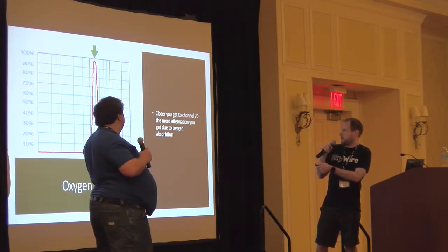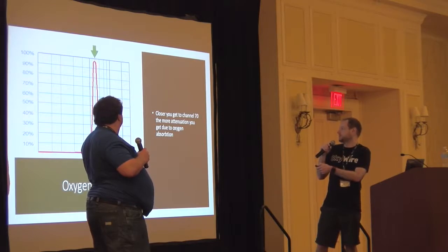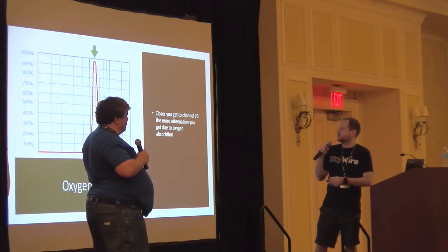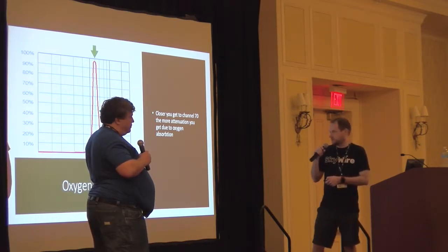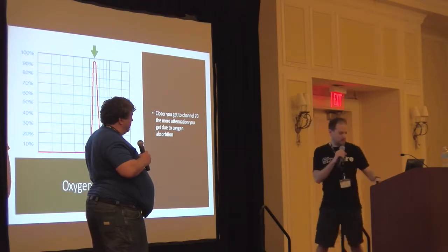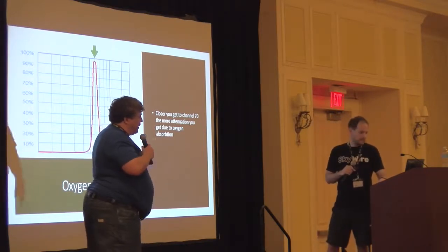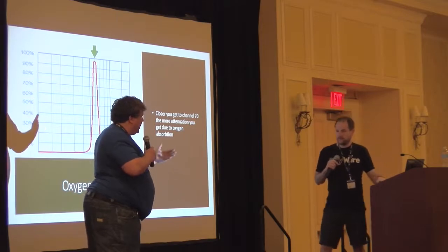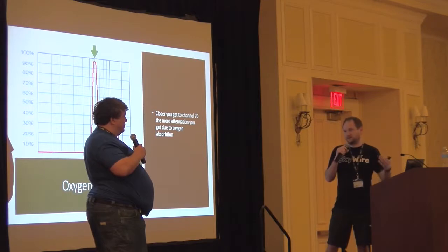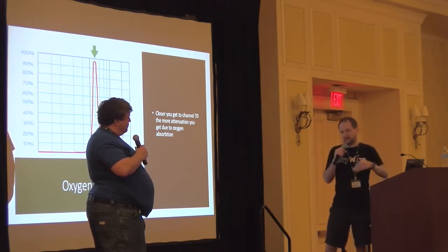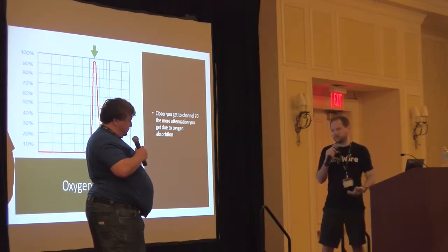When you're in the 58 gigahertz channel, the oxygen absorption is highest, and as you go up higher in the channels, it drops off pretty dramatically. When you're in 66 and higher, getting closer to 70, that issue really goes away, and you can go further. You were mentioning earlier that it's the opposite of 5 gigahertz. Yeah, it's the opposite. The lower the channel, the less loss you have in 5 gig, but in 60, the higher the channel is the better one.